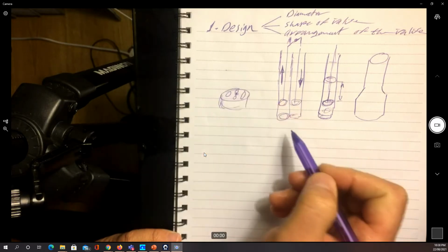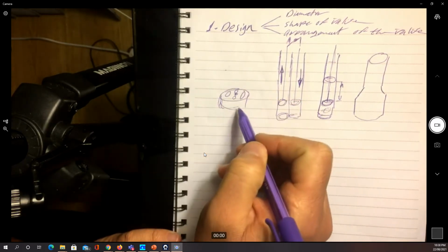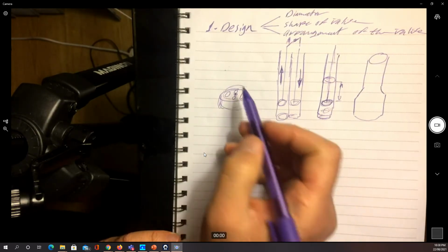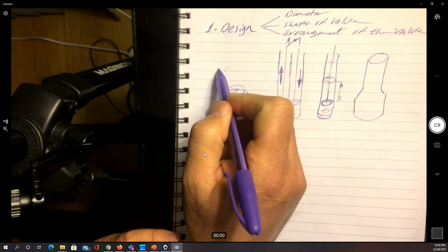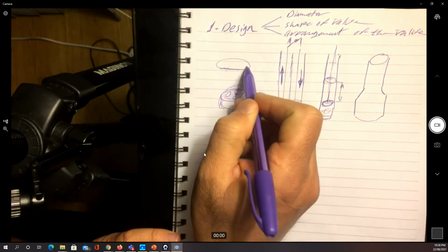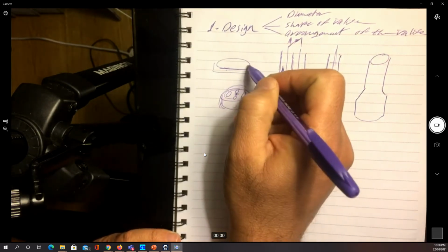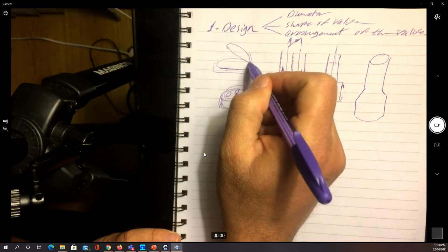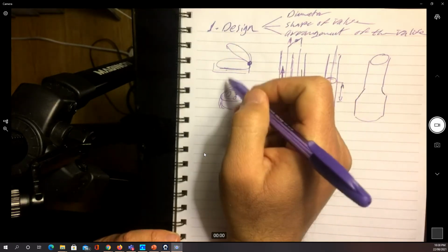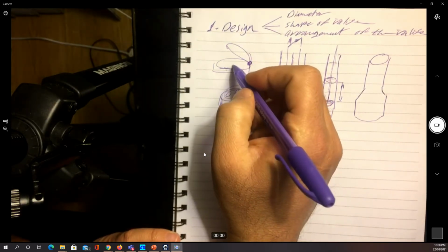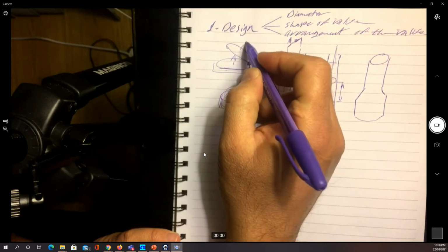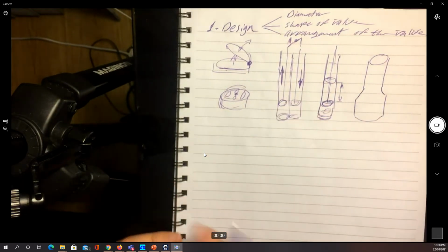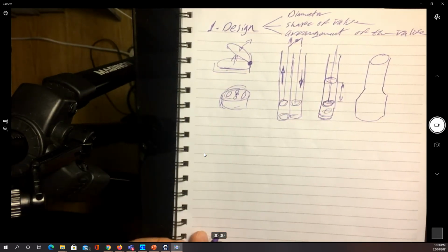For example, the foot valve, instead of being something like that with the seal at the top, which is the washer, we can have as a flipper shape. It's going to look like that, and it's going to have a circle door and a hinge here. As we pull, the water will push the flipper out, and when we push, it's going to send it down. That can be another example for the foot valve.